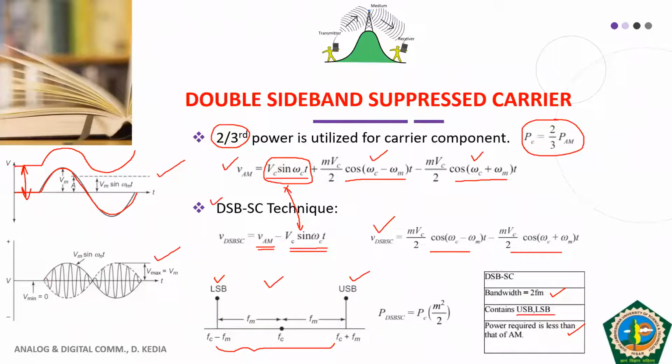And you can see here that in the modulated signal, the envelope is now touching the 0 line or 0 axis. Whereas in case of your original AM signal, it looked like this. Your envelope was looking like this, and your carrier was concentrated between this envelope.